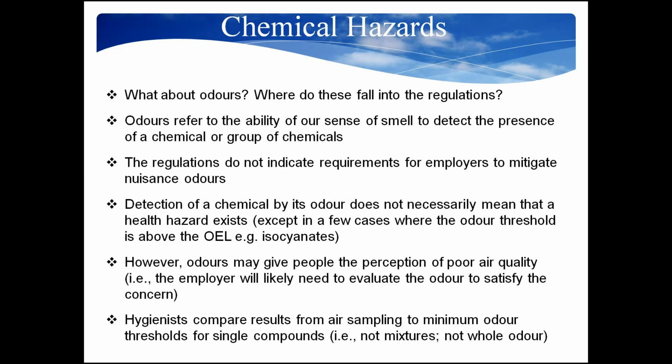So odors may give the perception of poor air quality, and the employer is likely going to have to evaluate the odor to satisfy the concern. Hygienists compare results from the air sampling to minimum odor thresholds for single compounds, but not for mixtures or whole odor. So when we get the results back, we can see which compounds are either above the OEL or above their minimum odor threshold.